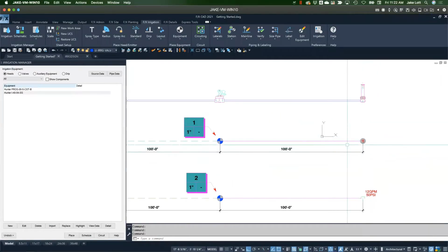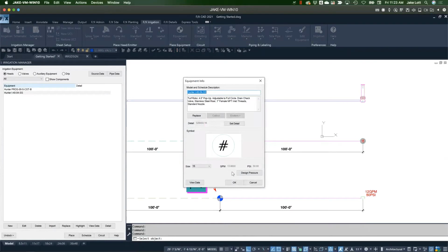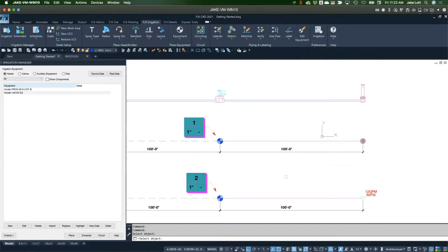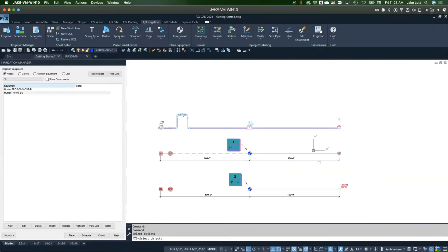And we're looking at this thinking, okay, what is my flow here? And I got 13.8. So I would be looking at the back of the book, finding that closest to 13, maybe 14 GPM, and doing the calculations from a friction loss standpoint. Now, this is where velocity comes into play. So we'll go ahead and size this so that we can start playing with this automatically.